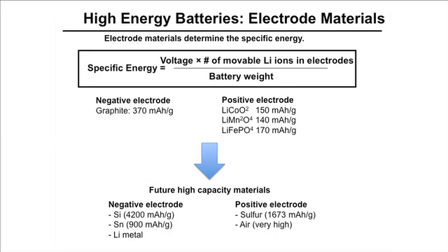Let me just focus on the high energy batteries. How do you do it? And let's analyze the state of the art. We know the energy is determined by how many charges you can store in the voltage, divided by the weight or volume. And the current technology, the best battery, uses lithium ion as the storage ions.